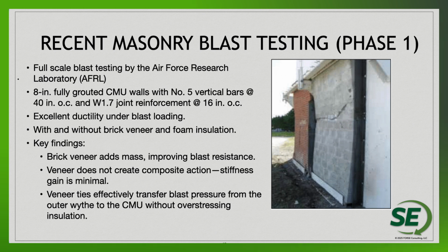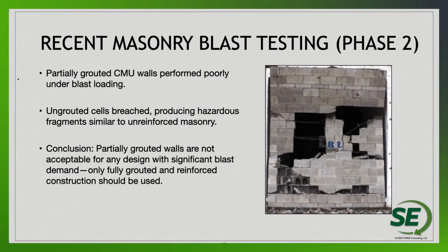And another important outcome of the study is that the veneer ties performed well, so they transferred the load without overstressing the insulation layer. And that's usually important to understand: the standard tie configuration, whether it can withstand blast induced loads or not.